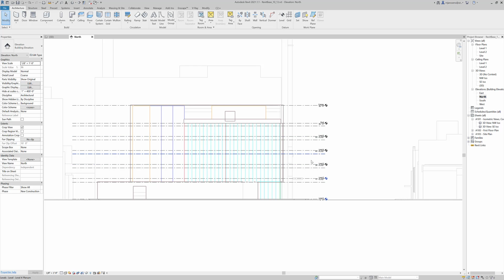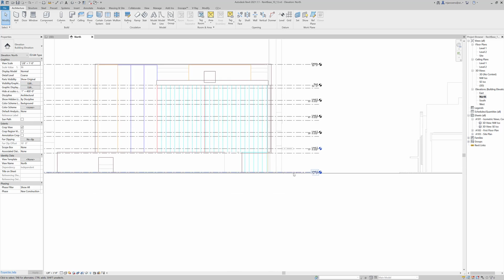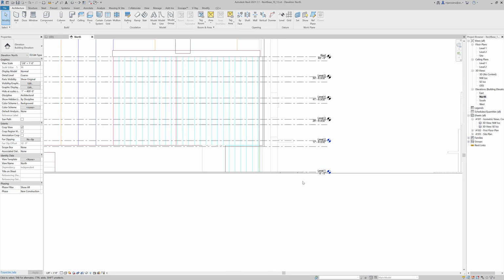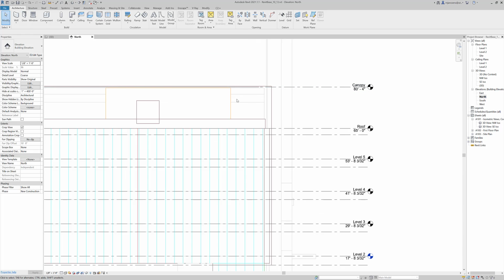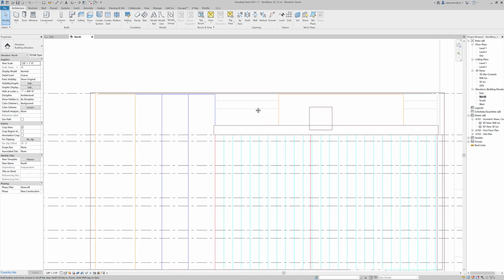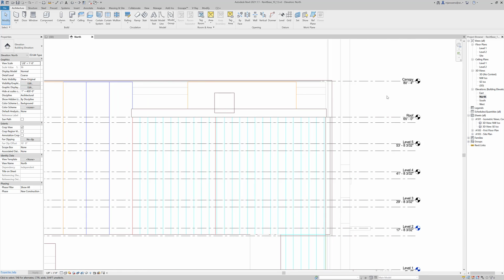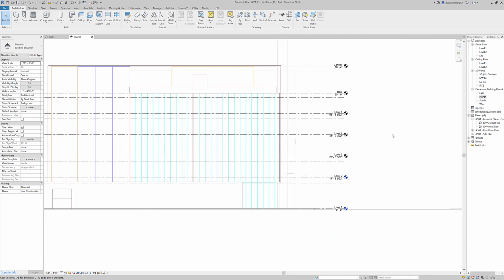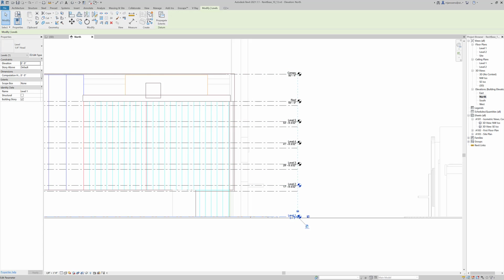Okay, so this looks good for right now. We can create levels in the future, and we might have to. We might have to make a basement level or foundation level or a spread footing level or something like that. And we'll probably have to have something here for the plenum of something like the elevator hoist or something like that if we need another level here. But you can see I have all of my levels kind of neatly arranged, and maybe I'll rename this ground.